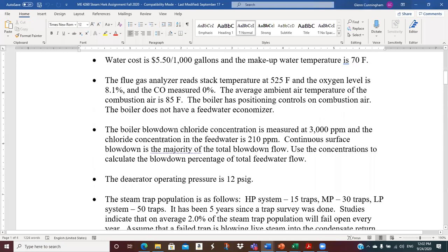And your boiler efficiency really should be 100% minus the stack loss, minus an estimated shell loss, which is probably on the order of 0.5%, certainly not more than 1%. But I'll let you estimate that based on the little information in the slides about estimating shell loss.